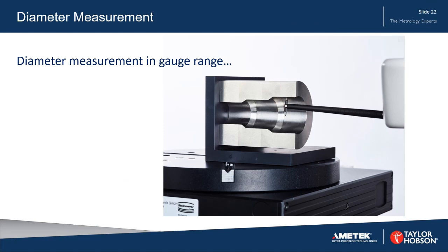In both cases, whether we're measuring large bearings or small bearings, the PGI Novus will give us excellent, accurate results for diameter measurement. One of the things that's necessary when we're using the column moves that we saw in the previous example is that the quality and alignments of all of the axes are very precise, and that the material and stability of that column is very, very critical if we're going to claim to be measuring diameter accurately.